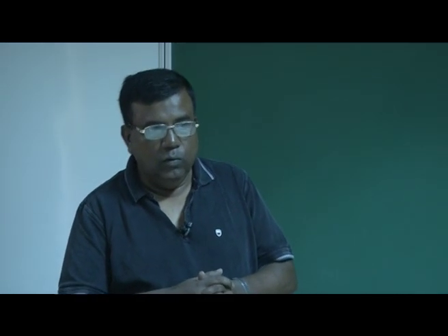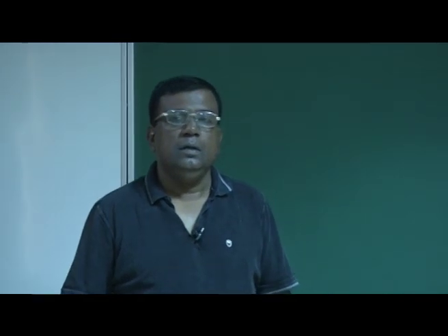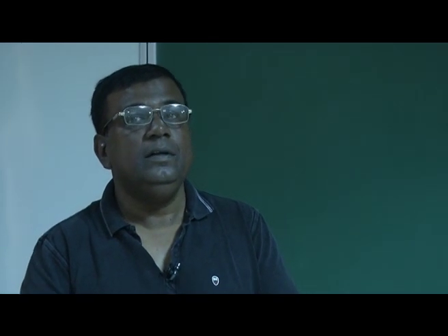Good morning, friends. We have so far developed equations of motion, and we have expressed equation of motion in body fixed axis system. And if you recall, we have u dot, v dot, w dot, p dot, q dot, r dot equations. And you all know why we are developing these equations of motion. We are very focused. We are developing these equations of motion to study the dynamic stability of the airplane.